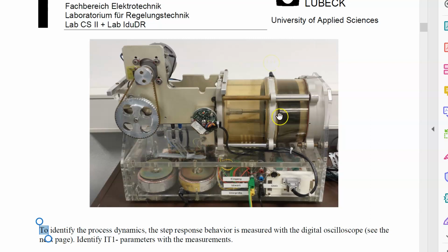In this experiment, of course, we don't want to do anything with breathing, but we want to move the piston backwards and forwards by driving this motor. So we have added electronics which has just a simple DC amplifier for the motor, and hardware which converts the movement of the digital encoder into a voltage. So there is a voltage in and a voltage out, and that is connected to a PC, and the rest is done on a PC. That is the hardware of experiment 1.